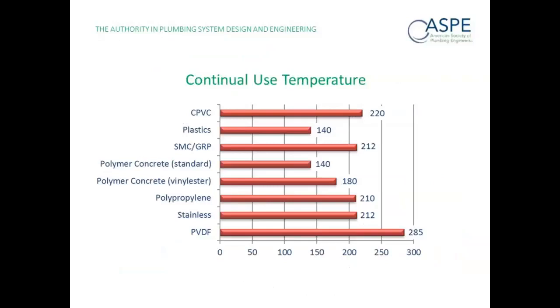You've got your continual usage temperatures here for various materials. And again, you also need to realize the limitations generally placed, and you can see that stainless is up to 212. It's the second one from the bottom. Now, that's not actually stainless steel. Stainless steel can withstand a lot more than that on temperature. I think specifically in this slide, it's to do with an EPDM gasket that's installed in the hub end of the push fit pipe, right? And that can be up to 400 degrees.